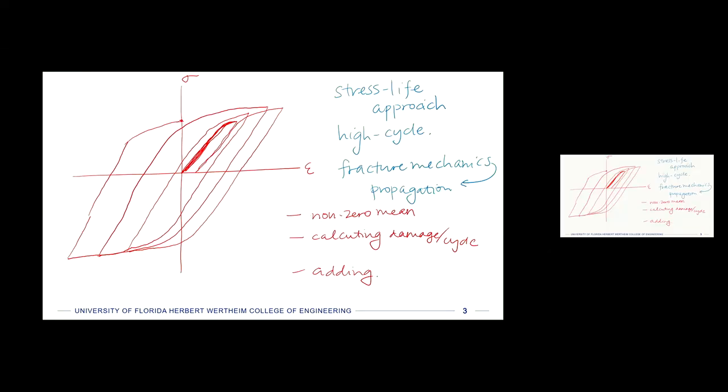So there's 3 stages of crack growth. I'll talk about them in more detail in a minute, but stage 1 is barely detectable growth. Stage 2 is stable crack growth, and then stage 3 would be uncontrolled, very fast crack growth.